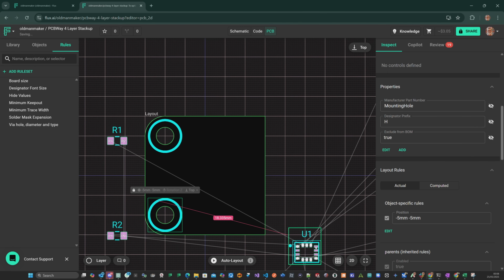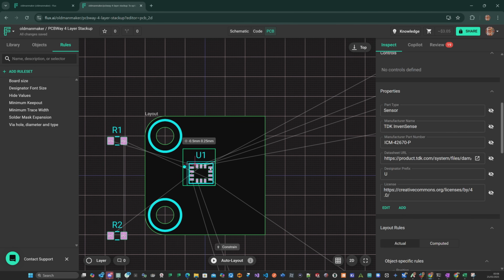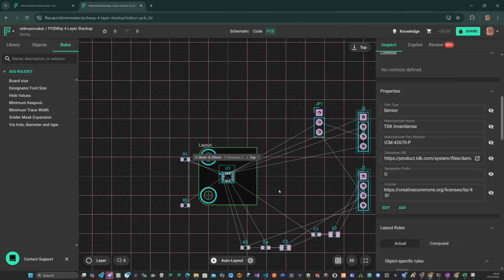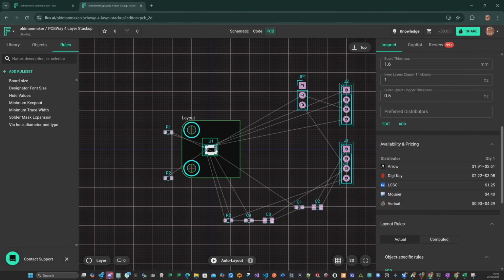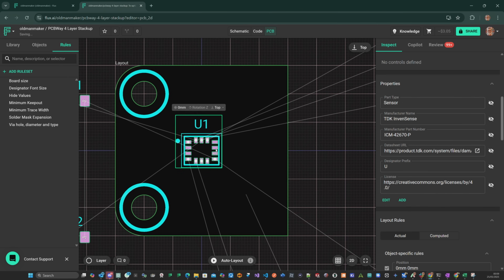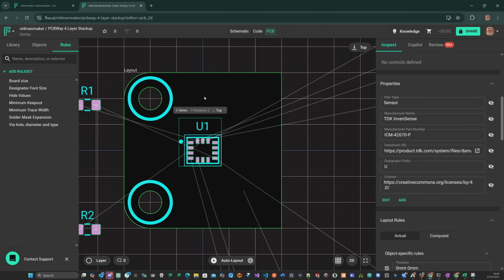Next, we're going to get our centerpiece sorted out. Now, not every PCB will have a single centerpiece chip, but there usually is a primary chip, for example, that you want to get positioned first. In this case, we're dealing with movement, so I want to get the chip placed in the absolute center of the board and then lock it as well.